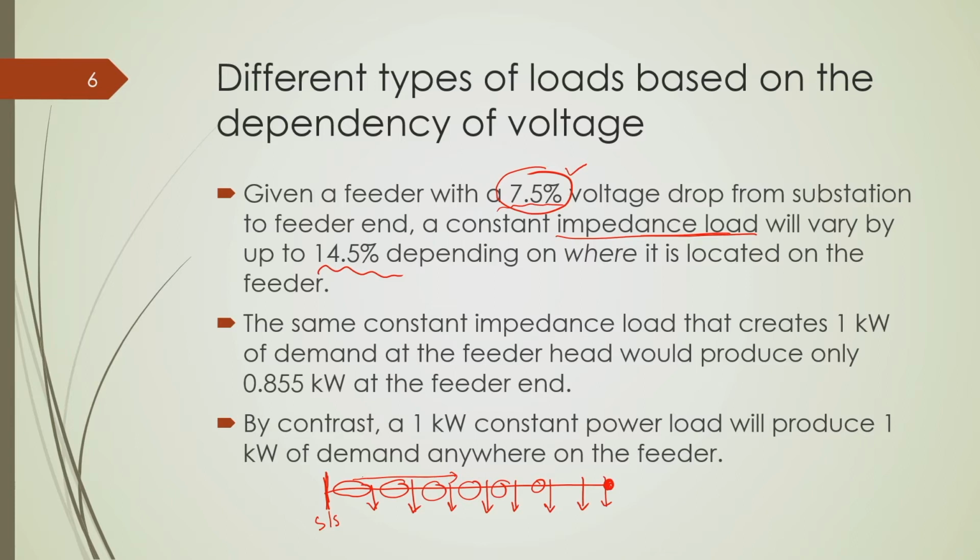Okay. So, one has to understand that although the nameplate rating is given to you, that does not mean all these appliances consume power based upon their nameplate rating. If a device's power demand varies with voltage, then obviously its demand will differ from its rated power demand based upon the voltage condition at that point of the network.